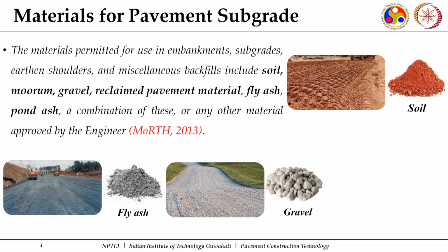As per MoRTH 2013, the materials permitted for use in embankments, subgrades, earthen shoulders and miscellaneous backfills are specified. Wherever any filling is required to raise the level of the ground, we go first for embankment construction, thereafter the subgrade construction.